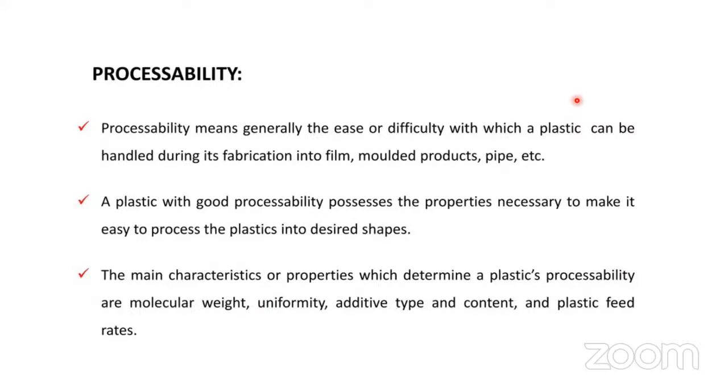For example, if you see Teflon, polytetrafluoroethylene, it's difficult to flow. If you see ultra high molecular weight high density polyethylene, it also has a high molecular weight and therefore is very difficult to process, friend. It is not easy to process on a simple injection molding machine.